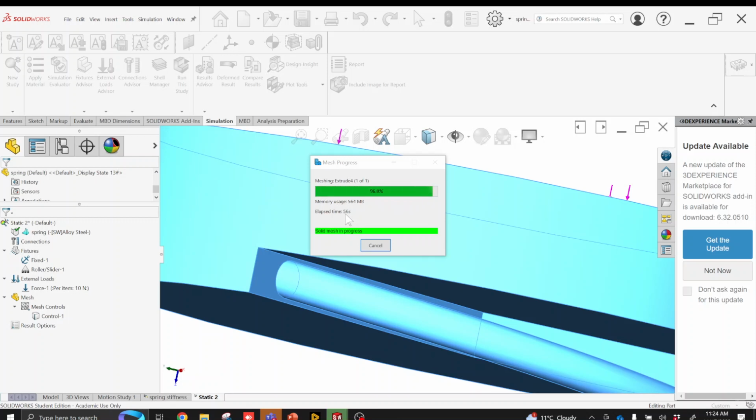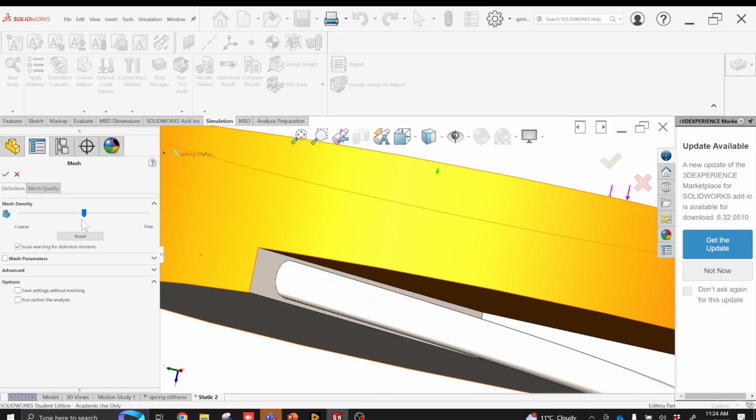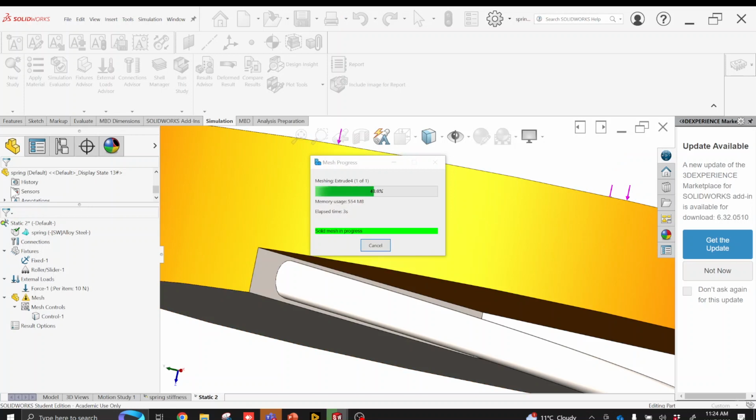of magnitude longer now. If you go and run, you can see, okay, I want to create a mesh, and I want it to be as coarse as possible. Ideally, if you had time and you didn't want to do this live, you can do the default setting for that, and then understand where you need to refine or coarsen from there. But we'll see how this kind of works here.